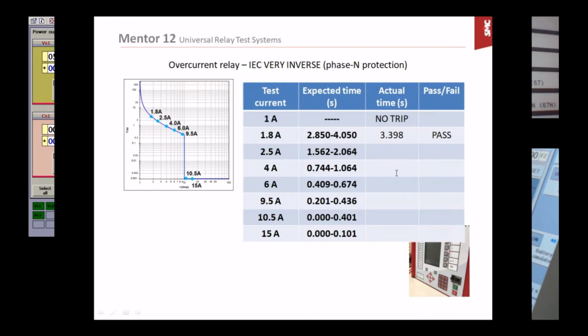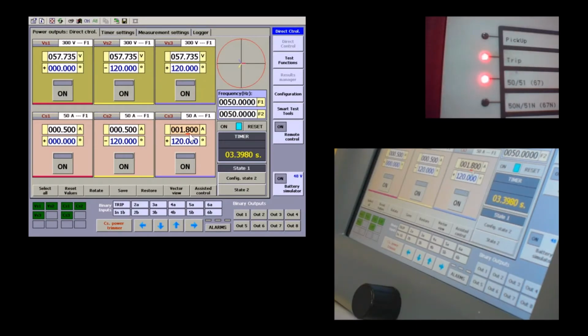And go to the next point, which is 2.5 ampere. Adjust 2.5 ampere here. And start. When I start, you will see that the chronometer will restart from 0, and also that the pickup LED in this camera here will start lighting again. I will now reset the other 2 LEDs which are engaged, okay? Just notifying a previous activity. Okay, so we start the test now.